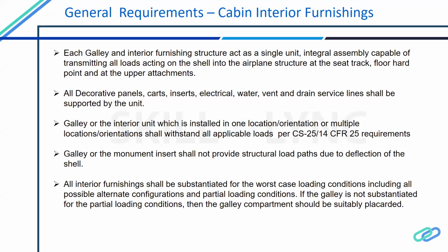And the other thing is, all these cabin interior monuments should be substantiated for all the worst case loading conditions, including crash inertia cases, and for different configurations. There are different configurations in the case of cabin interiors, because some of the cabin interiors have a baby bassinet attached to them, and a bassinet is just a place where the babies will be put to sleep.